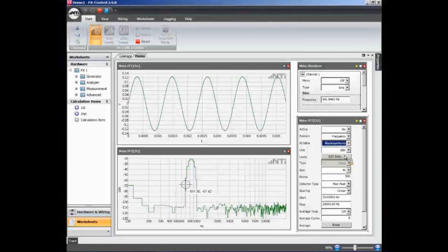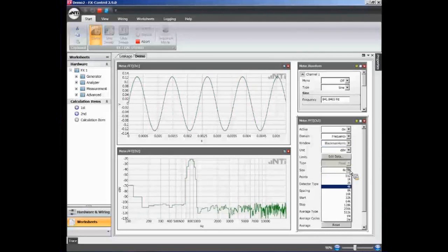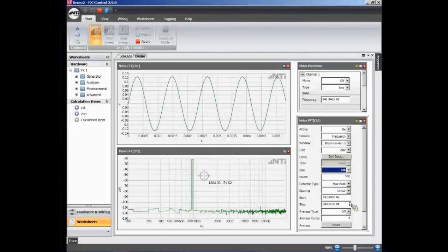First of all, this harmonic or this fundamental frequency is pretty wide. Can we do something about that? Yes. And the second point is you may notice that it seems as if the frequency spacing in the low frequency range is higher than in the upper range, and I will come back to that in a minute. But let us start with the width of this spectrum, of this bin. That has to do with the resolution, with the block length of the FFT. If I increase the block length, I get a higher resolution, and we get closer to the picture that we also saw before, that we would expect a very neat and narrow bin at the corresponding fundamental frequency.